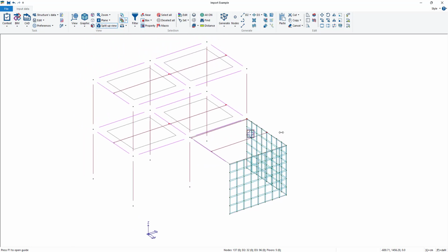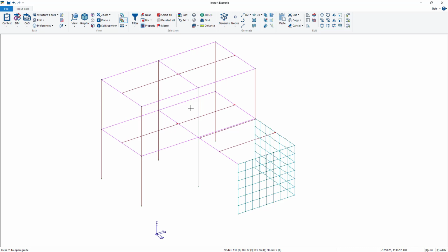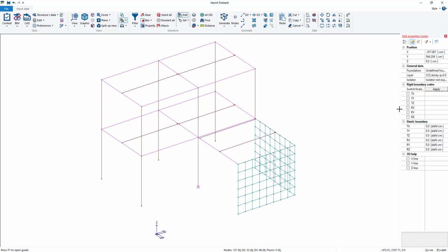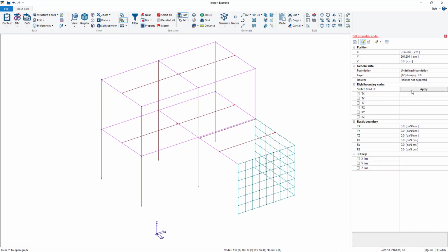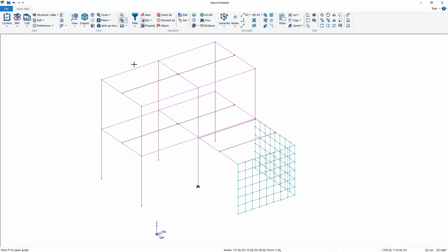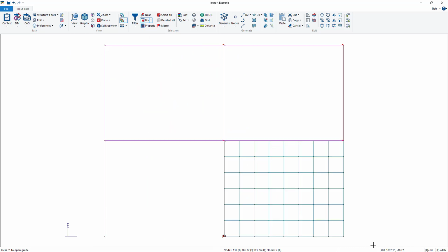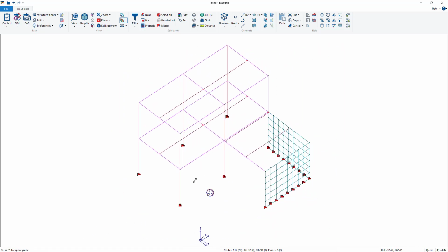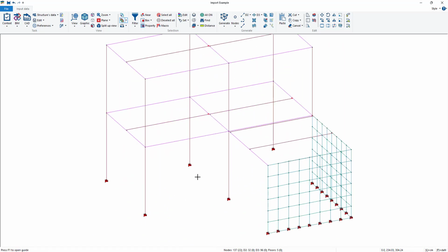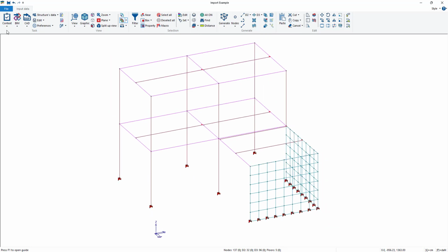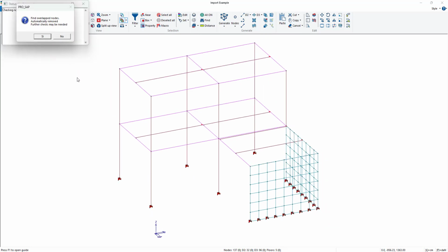It seems so. And okay, what do we need now? Just to apply the external boundaries on the nodes. To apply set reference, we can move to the X plus view and with box select all the nodes. Right click, assign reference. And basically from here it's done. We can go to the check structure data.